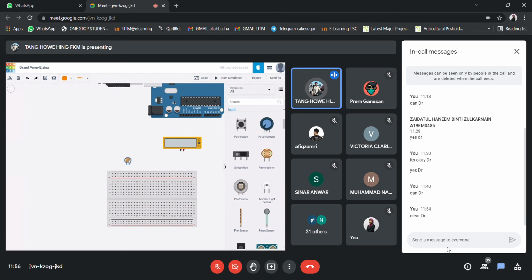Right, so first of all, let us determine the resistance range. Just now, although we have already tried it out, I've forgotten the resistance range. Okay, I should be measuring resistance, not voltage. Right, when it is complete darkness, I get a resistance of 180 kilo ohm.